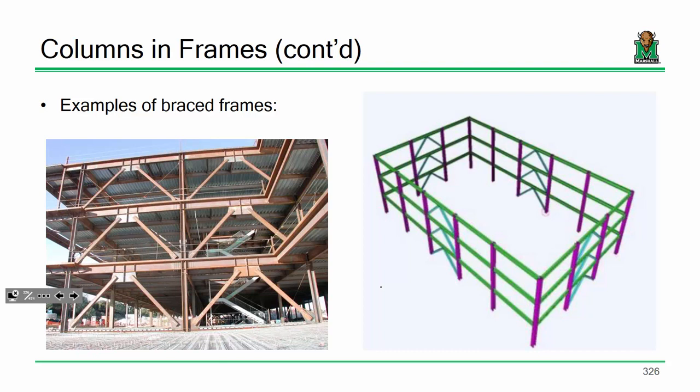The point is, when I apply a lateral load to this building, like a wind or seismic event, these braces are keeping the building up, acting as a truss. That's basically what they are. They're a truss. Here are your supports on the ground. You apply a load, method of joints, method of sections. You all remember that stuff, right?